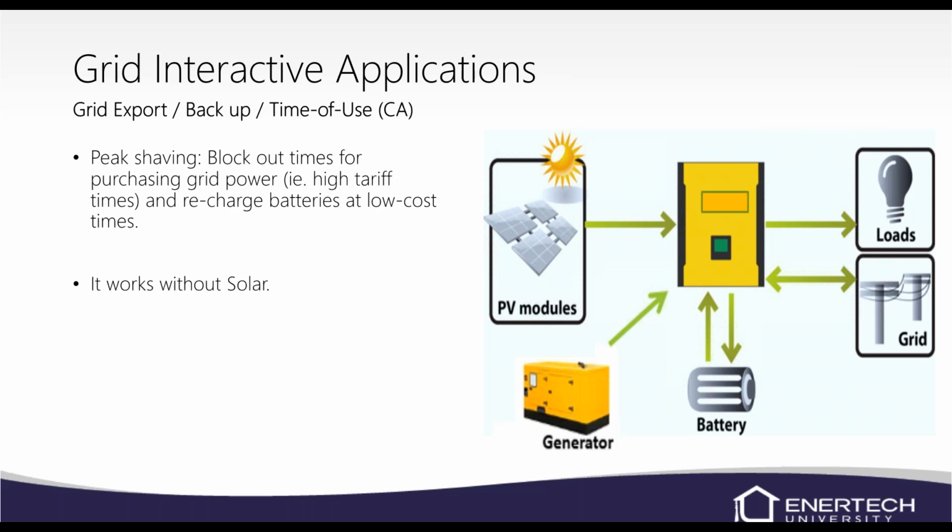And if you have a 12 kW inverter, you don't have to have 12 kW or more of solar. You can actually get by with like a 4 kW array on that 12K inverter. So you don't have to have an equal amount of PV when you do that. Cool.